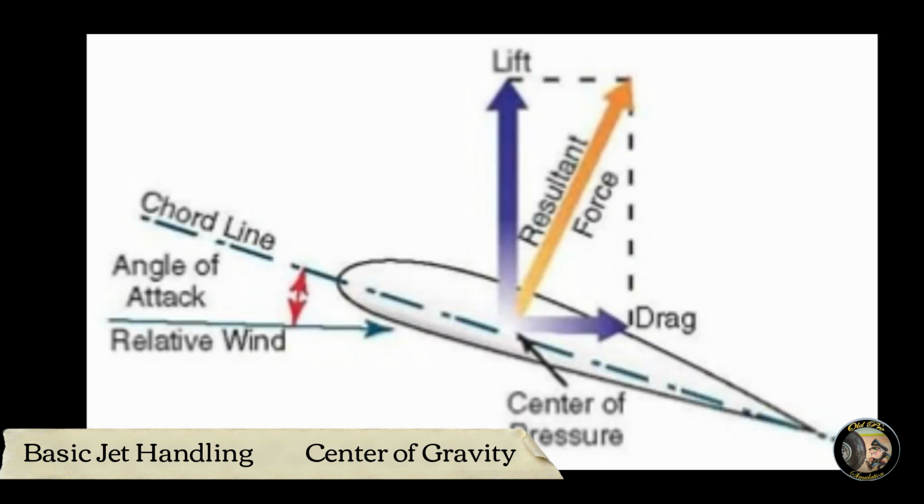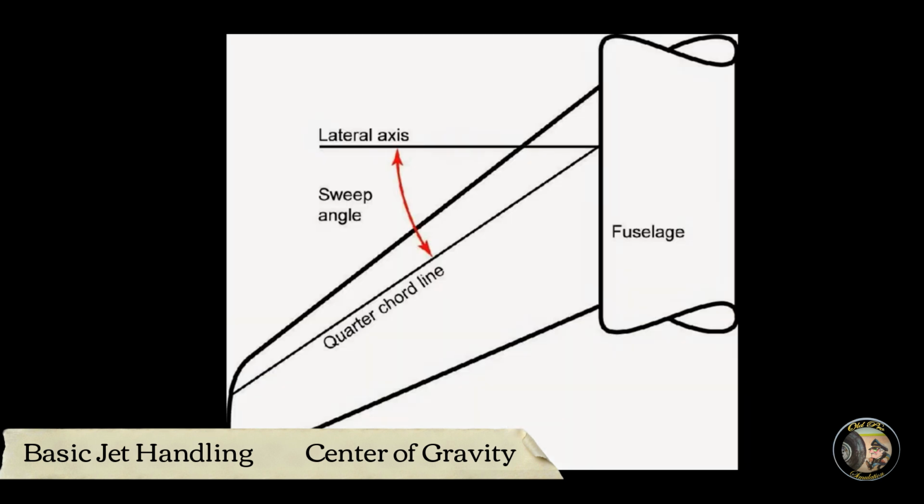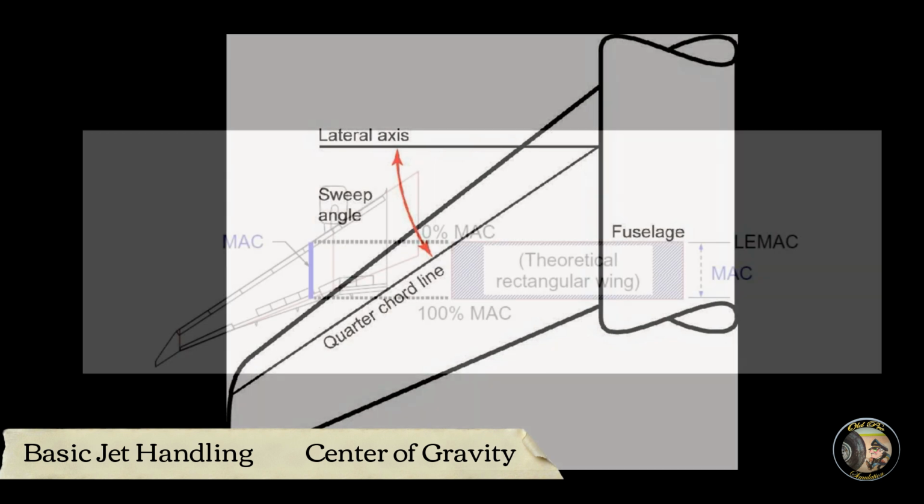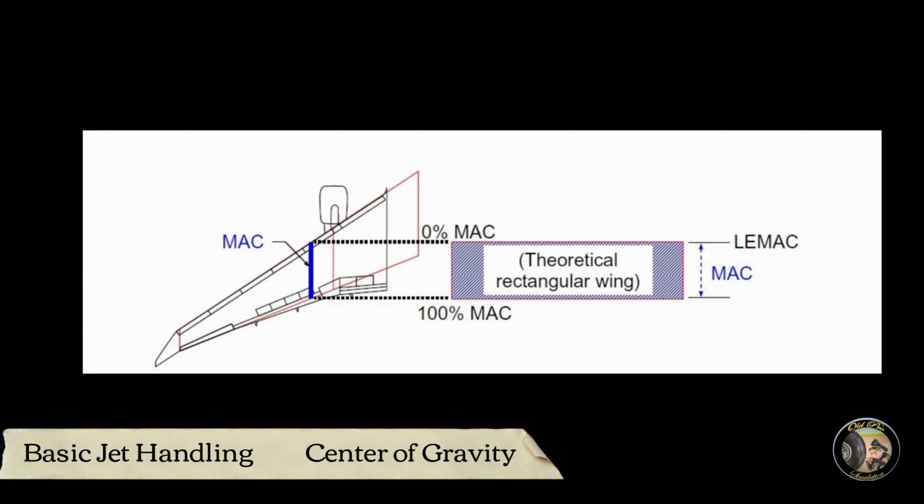On a straight-wing aircraft, we merely measure the distance from the front of the wing to the trailing edge of the wing, and that is the length of the chord. The quarter chord, or aerodynamic center as it is also known, is very easy to find in this case. However, with the swept-wing aircraft, the quarter chord moves aft along with the sweep and taper of the wing. What we need to do is mathematically convert this swept wing to a straight wing, and that'll solve our problem.